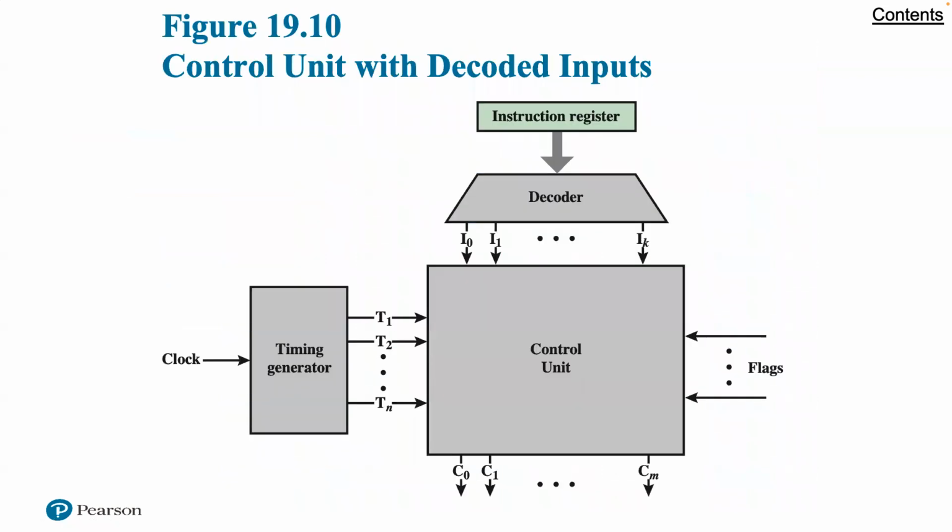The clock portion of the control unit issues a repetitive sequence of pulses. This is useful for measuring the duration of micro-operations. Essentially, the period of the clock pulses must be long enough to allow the propagation of the signals along the data path and through processor circuitry.